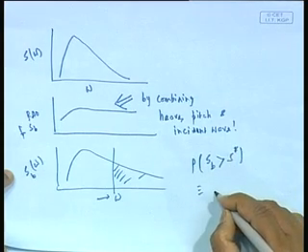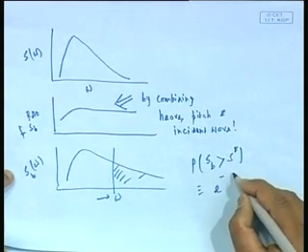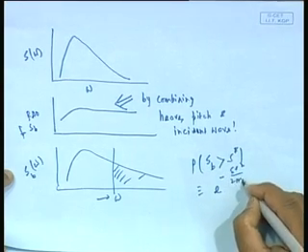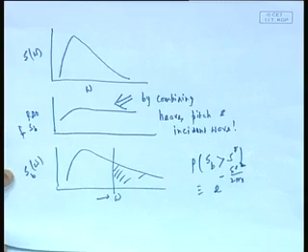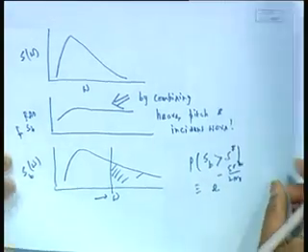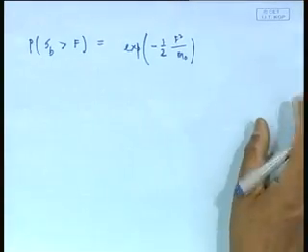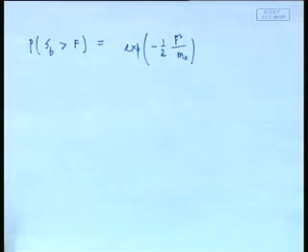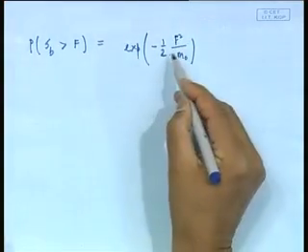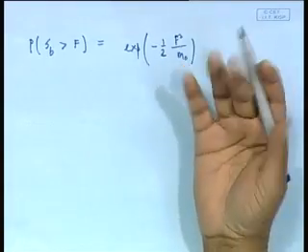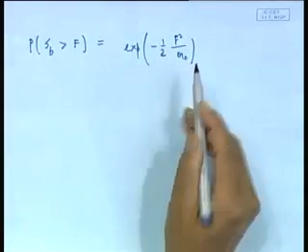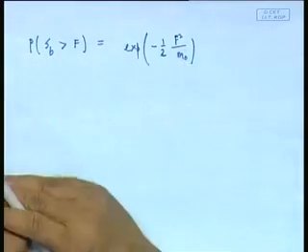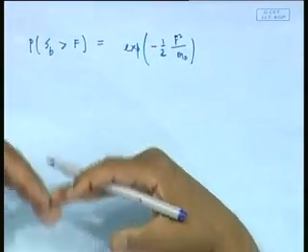This is always given by e power of minus s star square by 2 m0, where m0 is the area under the graph. So this is always known. So that means you always know this part. Not only that you know this part, see here my f dash is basically the threshold value. So what I say is that if SB exceeds f, then I am going to have deck wetness. So what is the chance of deck wetness then? Like this. Of course I can modify f, I will come to that part in a second, but from there I can find out all other statistical properties also.